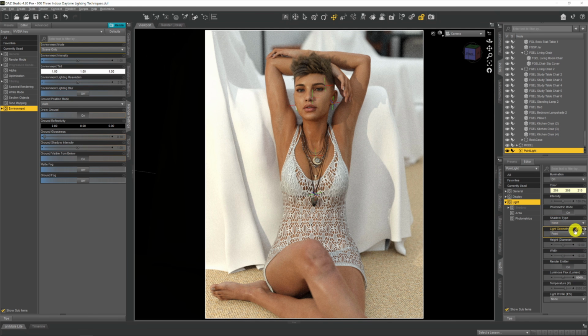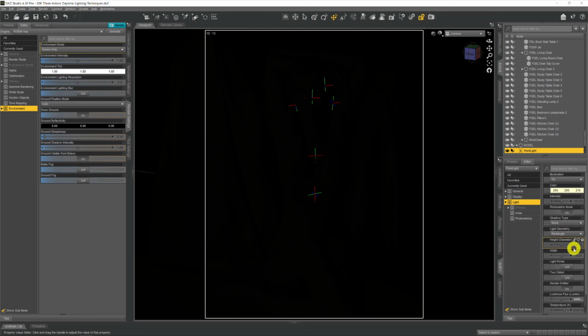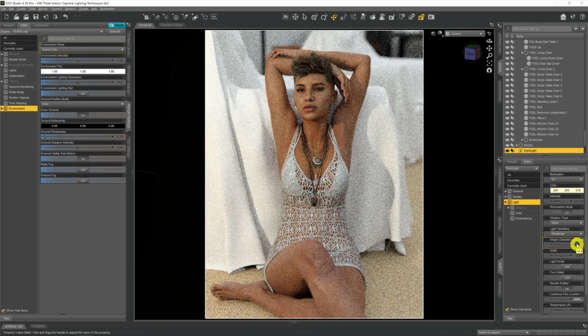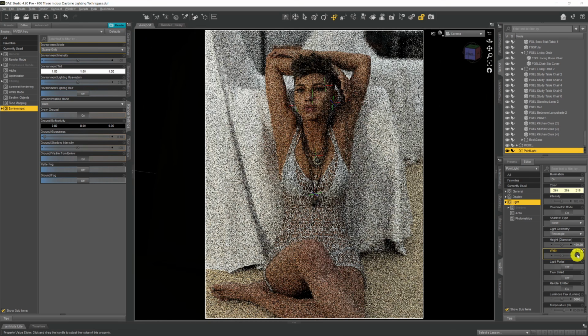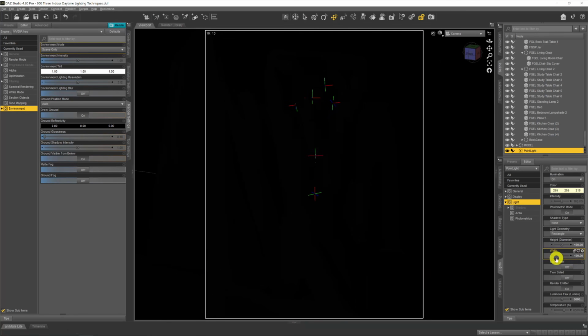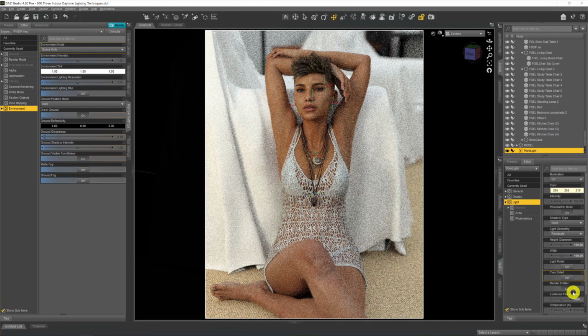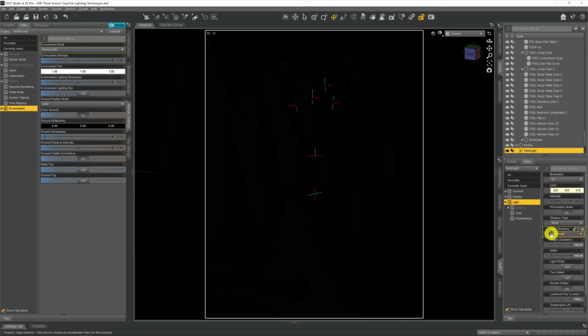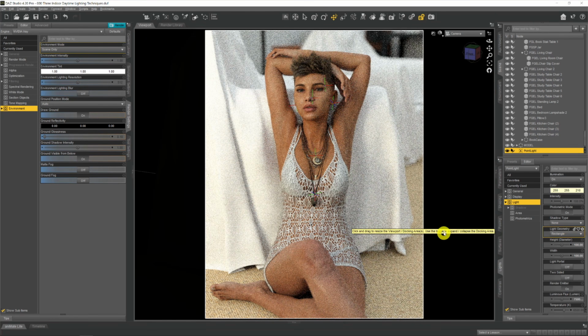So what I'm going to do is turn that light into a rectangle. And again, previous videos, if you don't know what I'm doing here, this is just me softening the light that's coming in from that spotlight, that point light that we've created. Check it out in the upper right hand corner if you're not quite sure what I'm doing or why. Now we've increased the size of that emitter, we just want to increase the lumens again so that we can get a softer sunlighty view coming in.